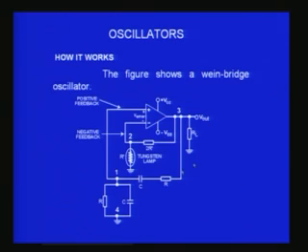but then when the current flows through that, it will produce a heat. So when the heat is produced, the resistance becomes larger due to thermal effect, and when resistance becomes larger, it will control the gain, right. The 2R by R factor will become smaller, and therefore it will provide a negative feedback to introduce a stability in the amplifier oscillator, and therefore it is normal to use a tungsten lamp in here.